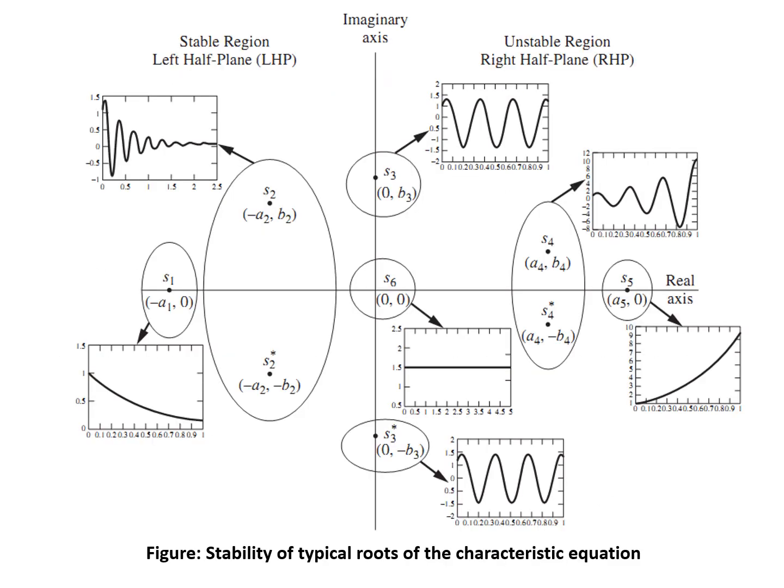Okay, we'll look at the location of roots on the complex plane. Why do we get a complex plane? Because the roots can be either real or imaginary, because the characteristic equation is a polynomial. So we have different locations here. If the roots are on S1, on the left hand plane, the stability criteria says it is stable, and the shape of the response is an exponential decrease. So this is a stable system.